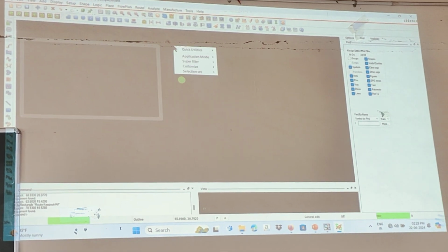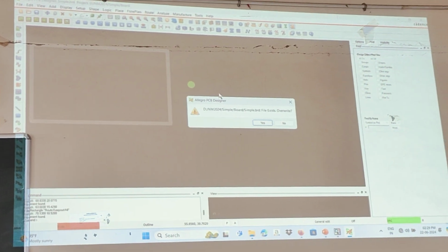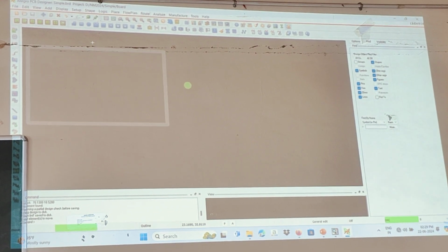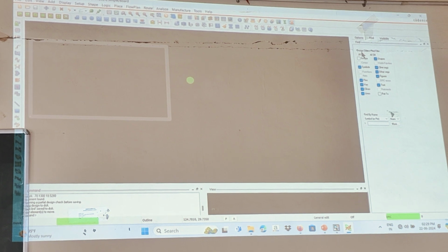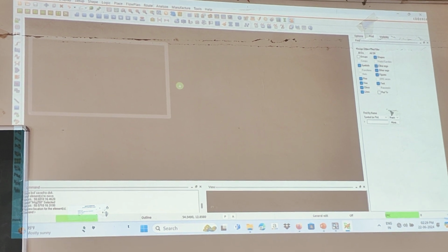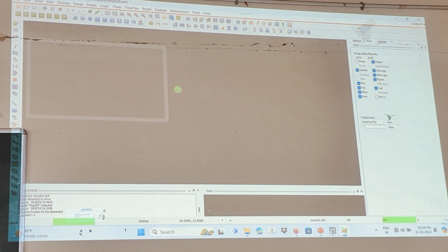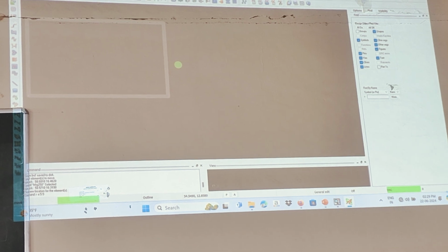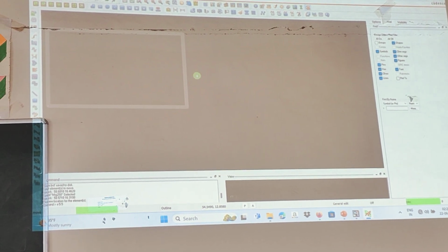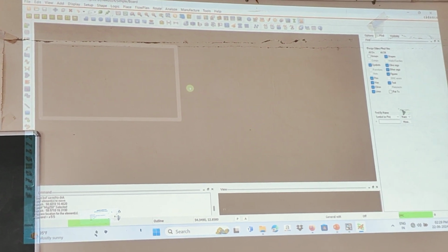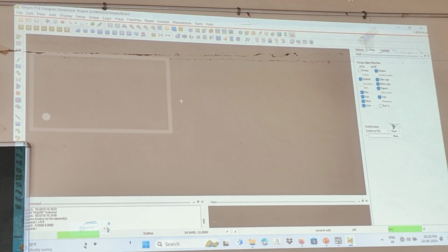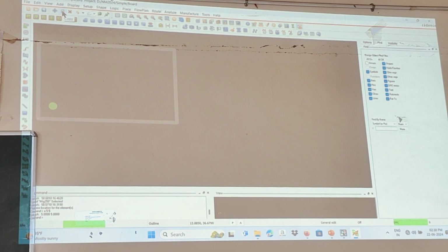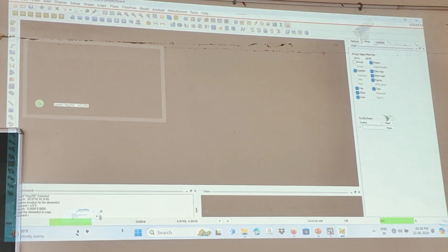Now I am going to place the mounting drill at the four corners. So I am going to move the pin. X space in the command window, X space 5 mm space 5 mm. In X and Y, I am placing the pin at the 5,5 coordinates. And right click and give done. Now I am going to copy the same pin for all the remaining 3 corners.